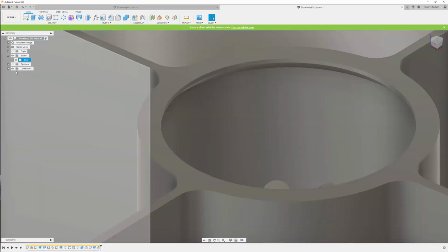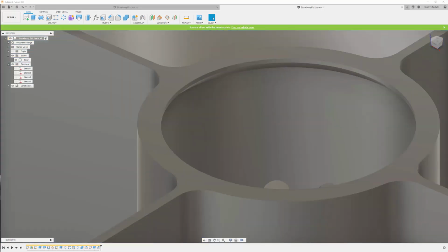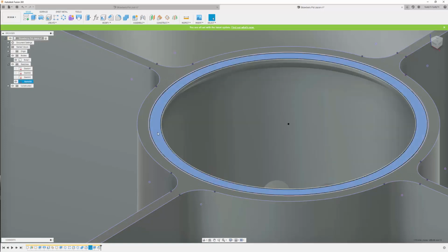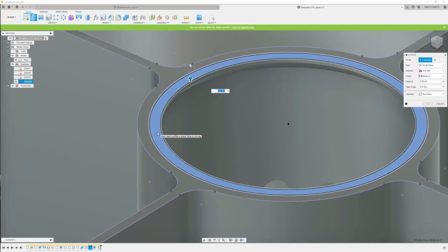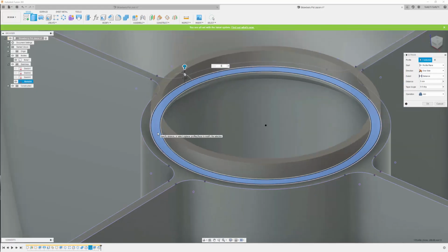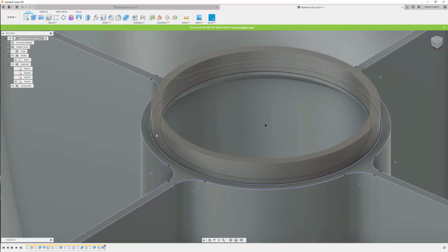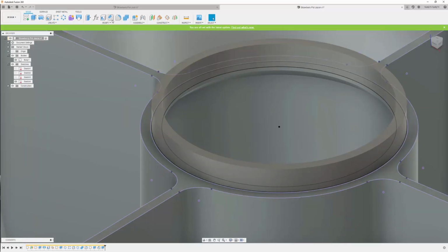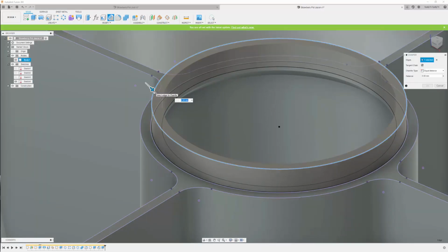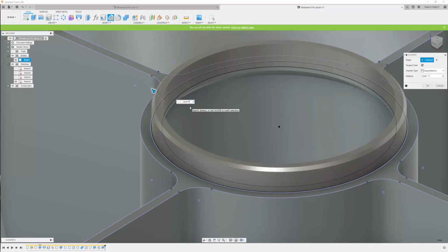So if I turn the sketches back on, turn sketch 6 on, now I can select this edge here, and I'm just going to go extrude, and this time I want this to go 5mm. So now it's creating a 5mm wall, join. Once again, to make life easier for the fit, I will select that, and this time I'm going to put in here, once again, layer multiplied by 3. So it's going to be a 0.6 chamfer.